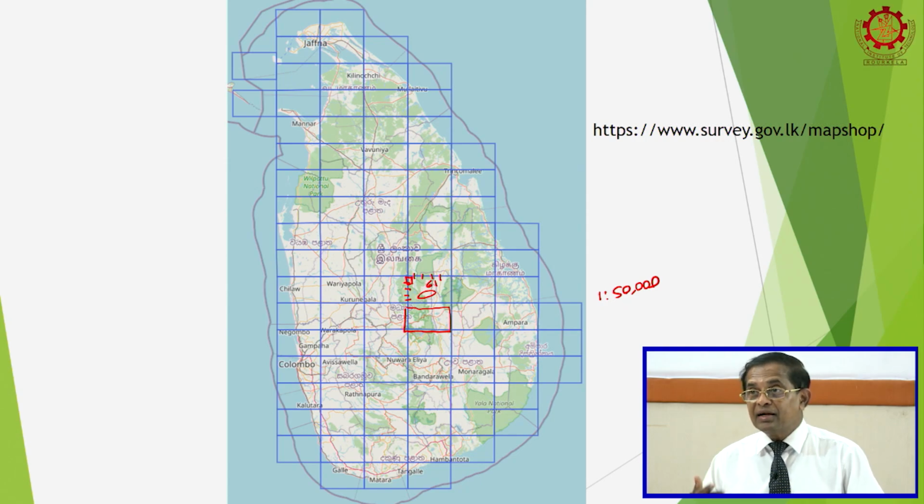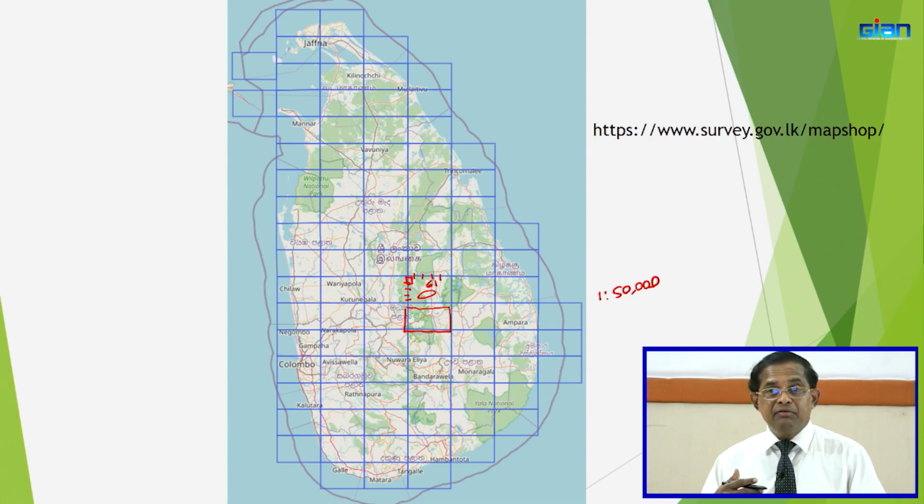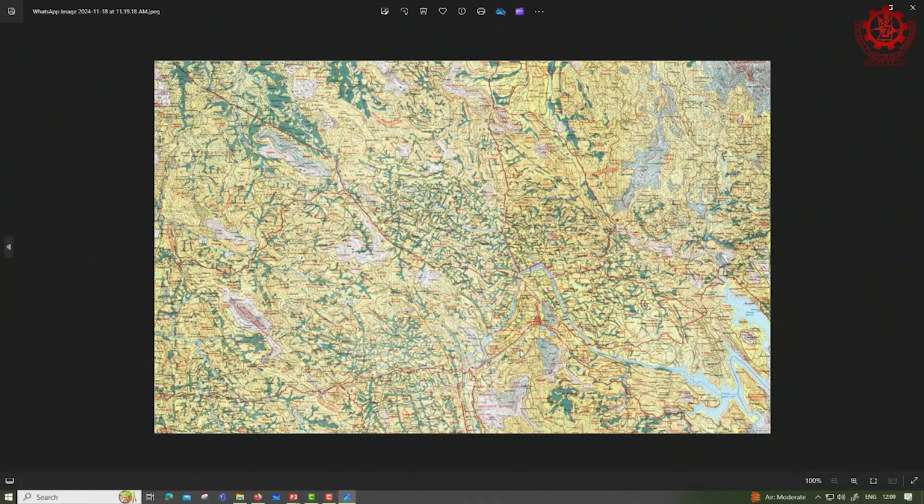Even if you are doing an agricultural project using a large extent of land, it is good to buy the contour map in that area, then to identify the land features, rivers available, and then the hills and other things, all the information will be available in the map. So, the contour maps are not only for hydropower development, they are for any activity you are doing as engineers. If you are mobilized into any area to do projects, it is always good to get the contour map of that location and to use them.